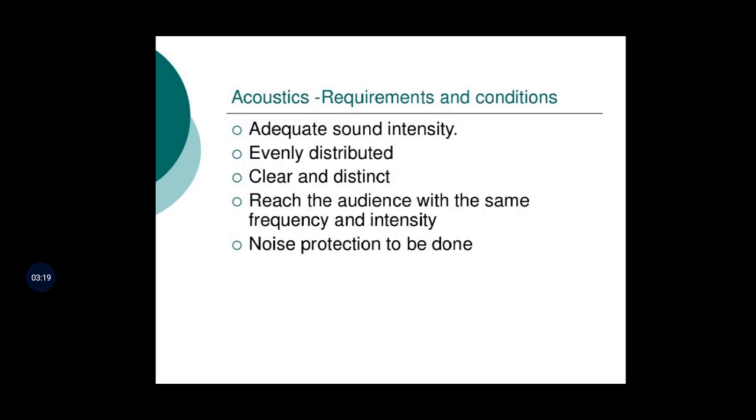Now next one, acoustic requirements and conditions. The following points must be covered as far as acoustical design is concerned. These are the requirements. What is adequate sound intensity? It must be there, evenly distributed. The sound should be evenly distributed, and there should not be any dead spot or sound foci. A clear and distinct sound means clear pitch and clear loudness; it should not be less than 20 cps.